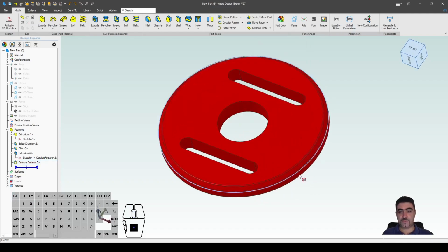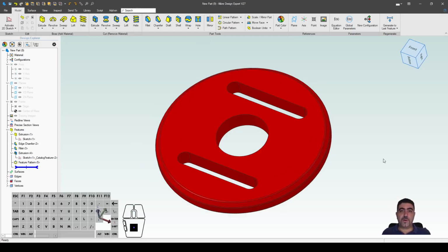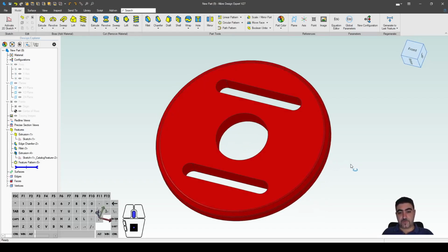Okay. And this could very well be a top mount for a McPherson strut that has an adjustable camber or caster or whatever you want to adjust with this. So you see that we put in these slots with minimal effort, right? And we even deleted one of the predefined dimensions and put in another one, and it still works.